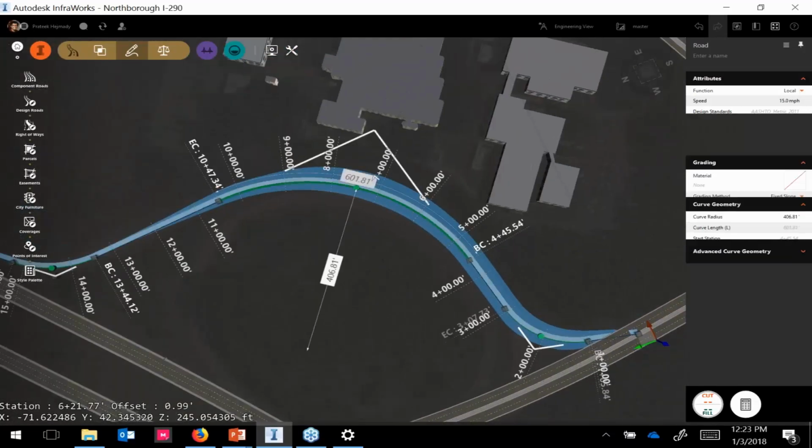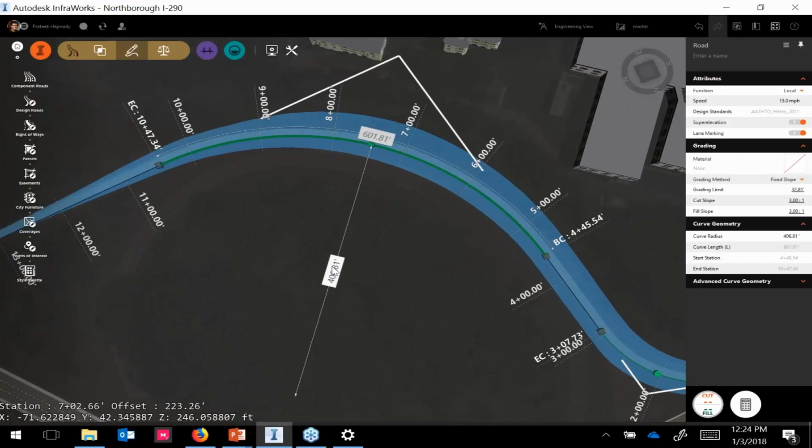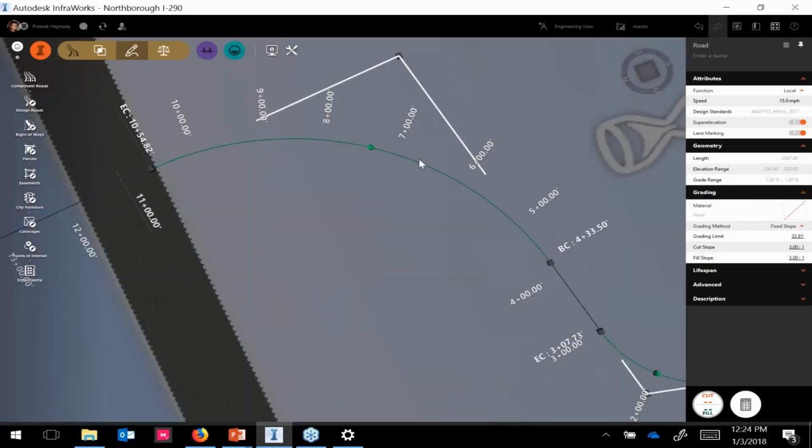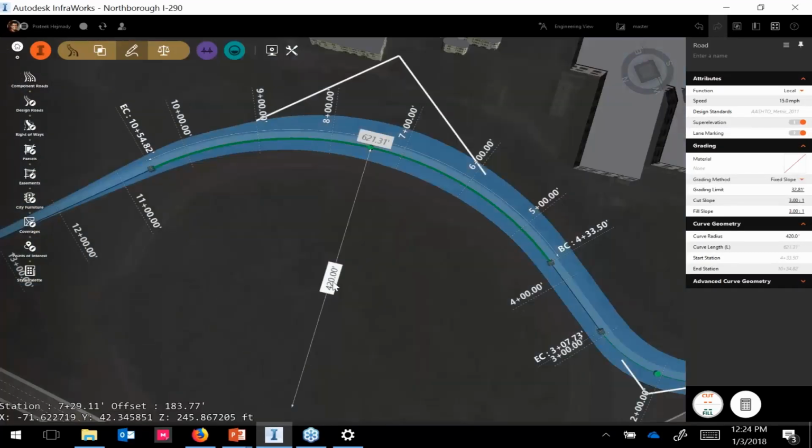When you do select a geometry, you will now see more information on the geometry right here in the canvas itself. This was not possible in the past, but now you start seeing these attributes. If you hit the tab key at this point, you could go ahead and edit the values as well. So in this case, I'm going to type in, say, 420. I could edit that right there, and that should reflect in the geometry. I could also directly click on that annotation, make it editable, and key in a new value likewise.